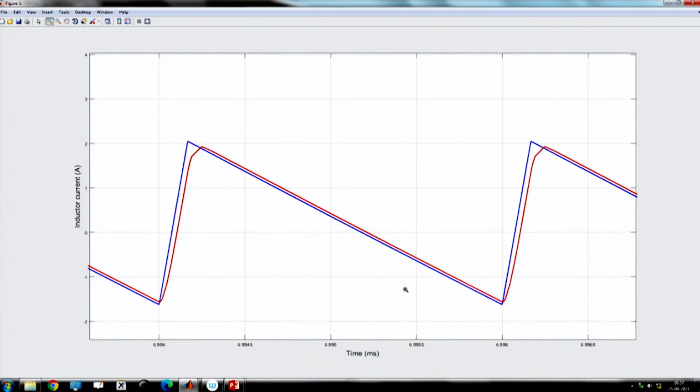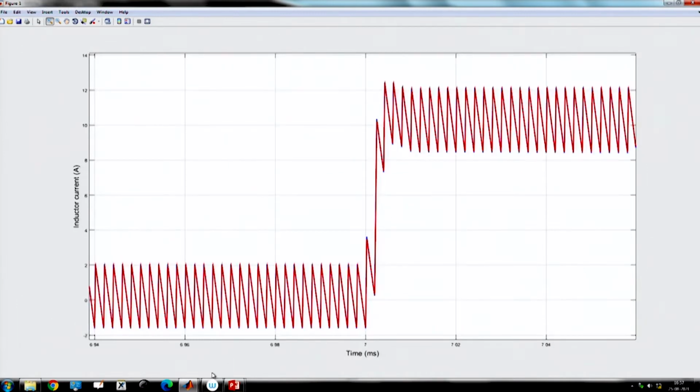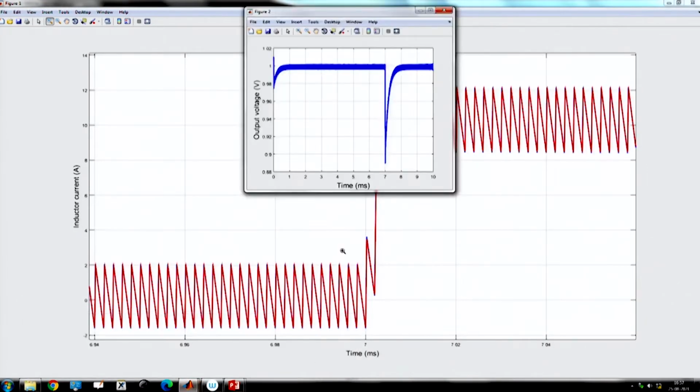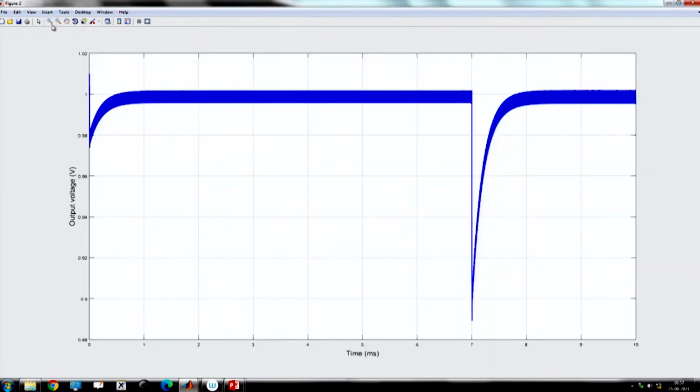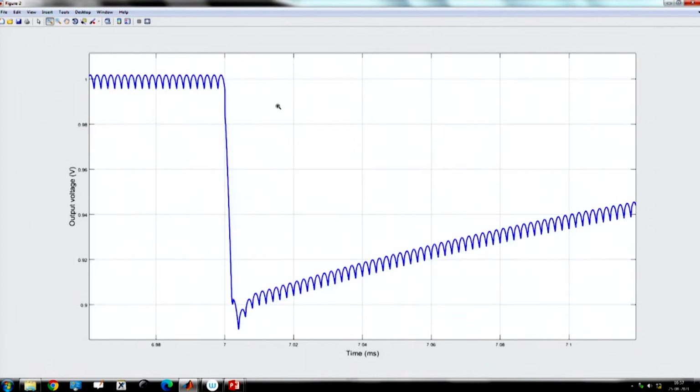As a result, it is somewhat smoother, right. So, you get close to the current waveform, but not exactly the same, and the response is pretty fast, because we have a very high bandwidth current sensor, and the transient response looks like the usual current mode control, a first order behavior that we can expect using this controller.